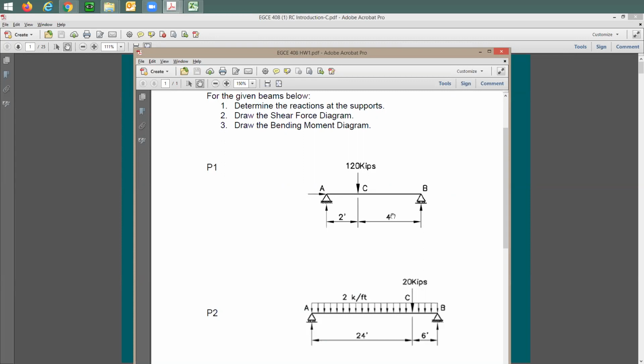And then after that, you need to come up with the beam size or the column size, and the amount of reinforcing that you're going to put there, to figure out how much it's going to be able to support. We call this the capacity. In an ideal world, you'd like to have capacity more than the demand, or at least equal to it. Does this make sense to everyone? Yes? No? Yes. Okay.